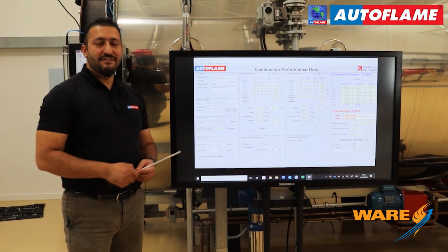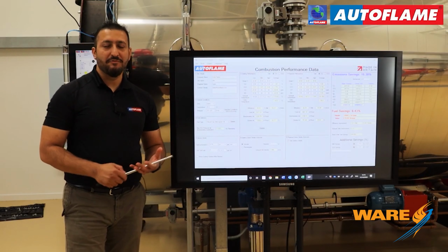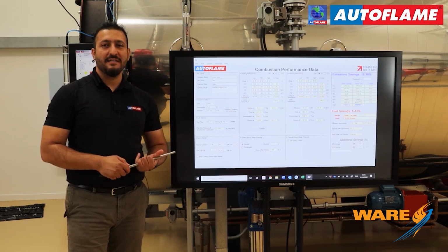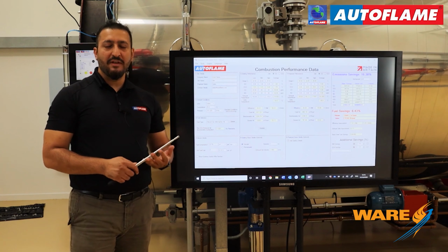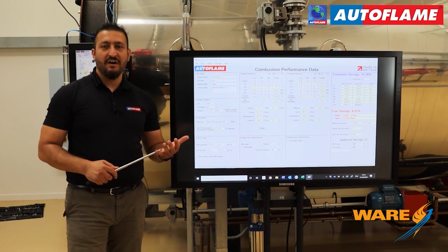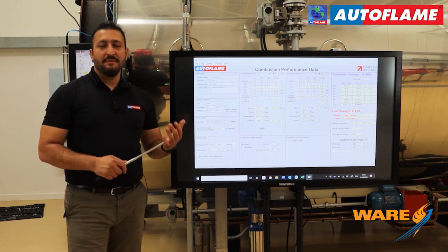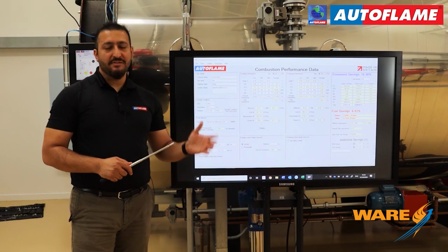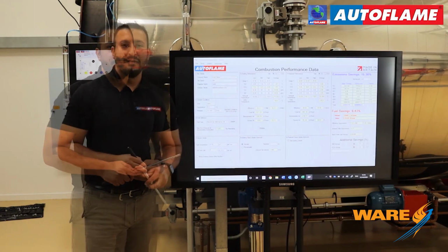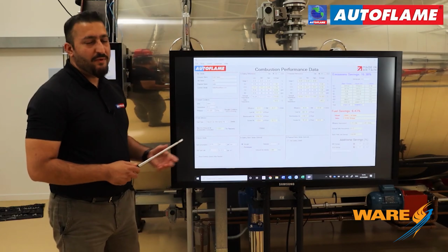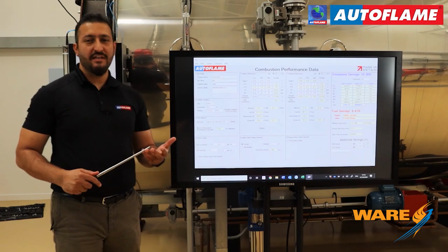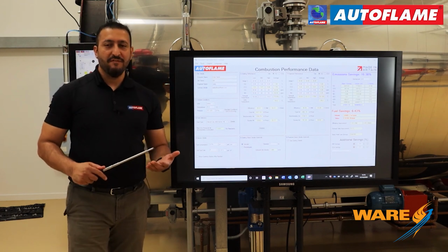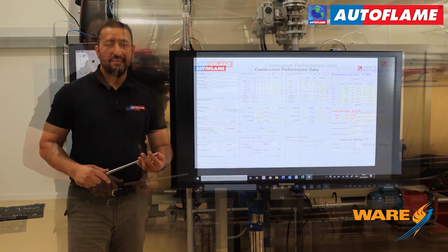In this latest version of the emissions calculator, we made some improvement as to where the performance data has been put in. So rather than taking an average reading, now we put in the data on low, mid-fire and high-fire position, with a percentage as to how long this burner stands on those percentages. In order to use this software, the typical data we need is the O2 readings, CO readings, your stack temperatures, your fuel usage and the fuel cost.